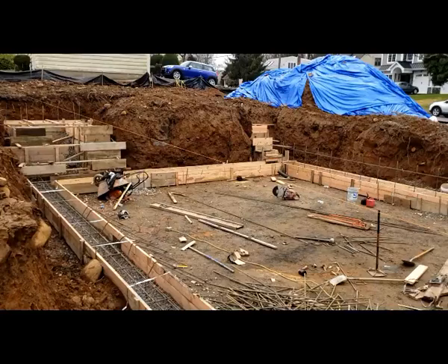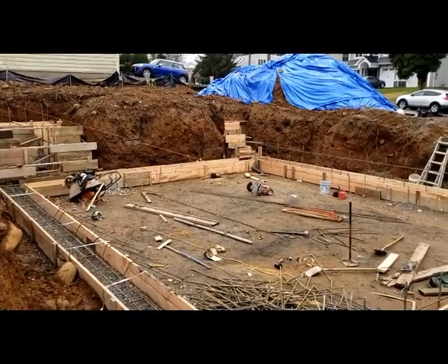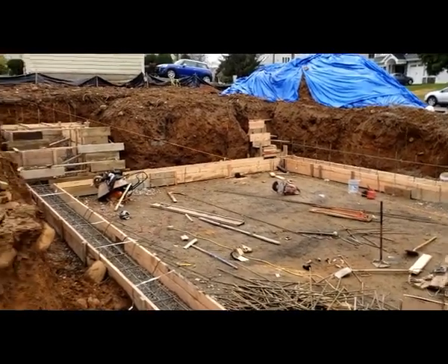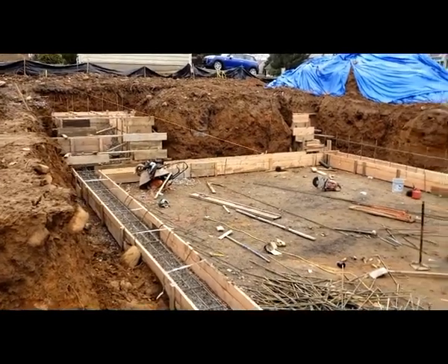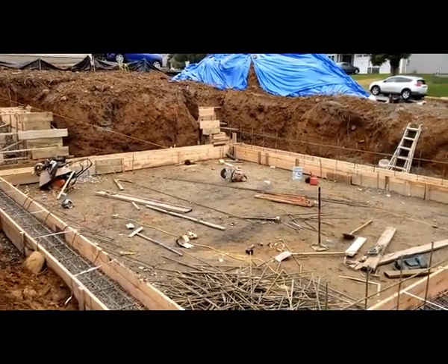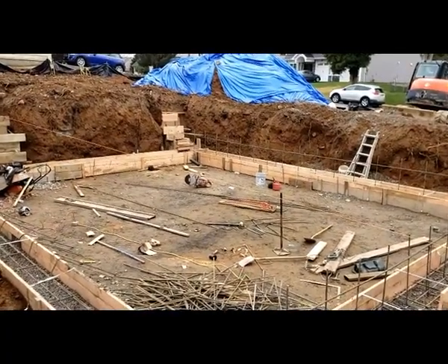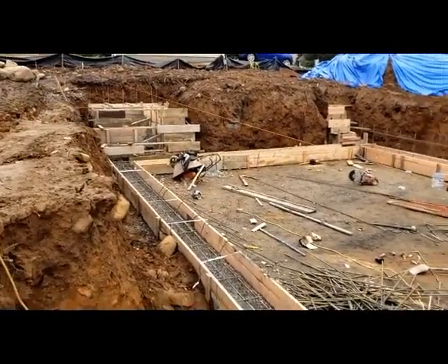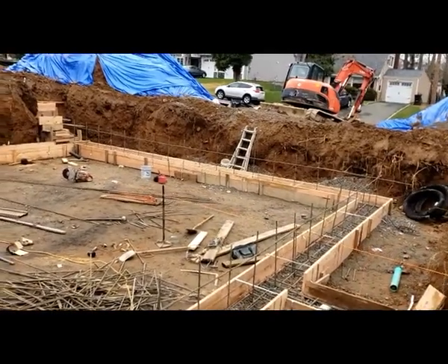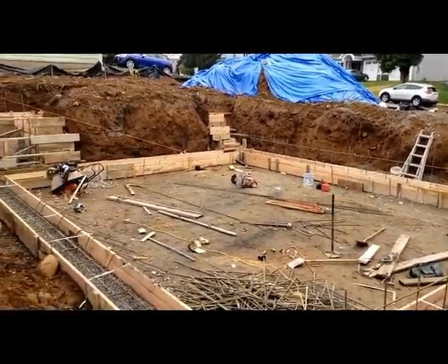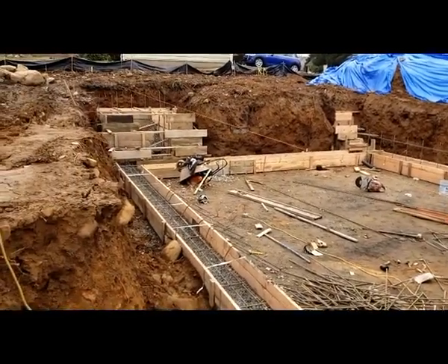Now, for the walls, usually they are panels, 2 feet, 4 feet, 8 feet. You want to make sure all the numbers add up like I showed you. TOW and TOF, top of the wall and top of the footing, all good. So number one, check with your contractors that the elevation is good.